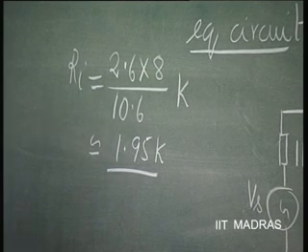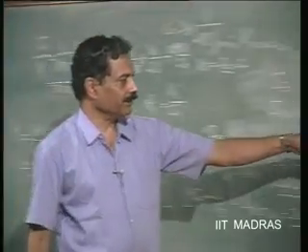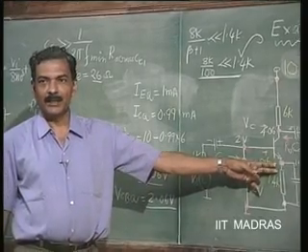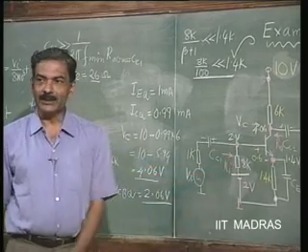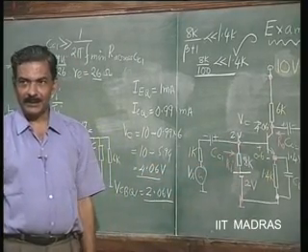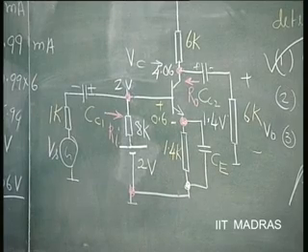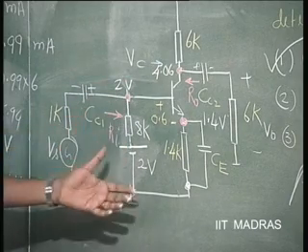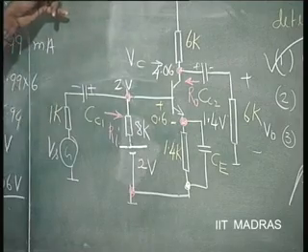Please note that it is 8 K, which is coming straight away here, and whatever is offered by the amplifier as 2.6 K. So, this 8 K is also taking away a certain amount of the signal current. Actually, in order that this should not take any signal current, it should have been of the order of 10 times 2.6 K or so, 26 K. So, the design is not good, right. If you make it too high, then it will not satisfy this relationship.